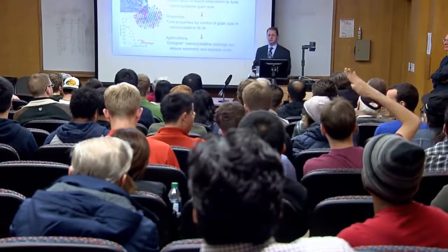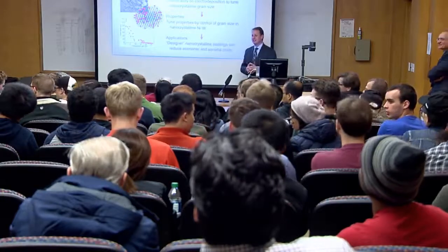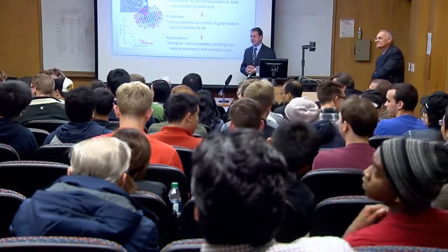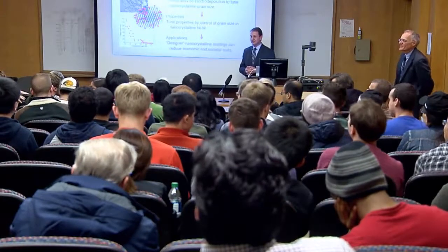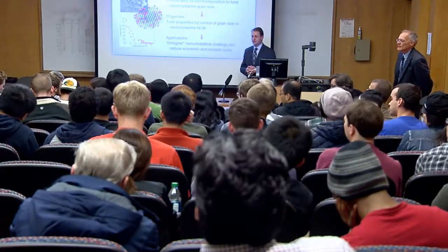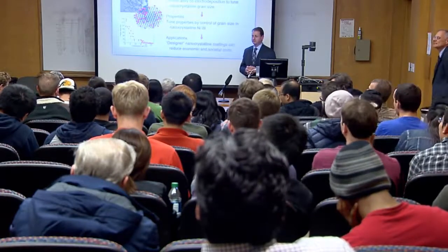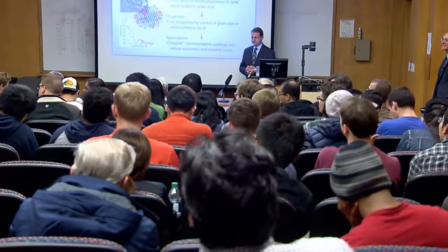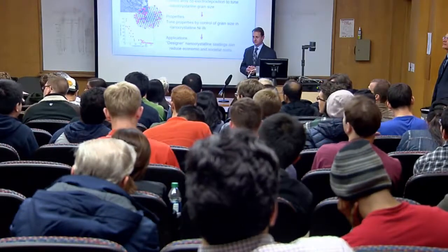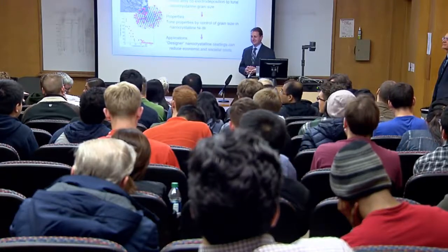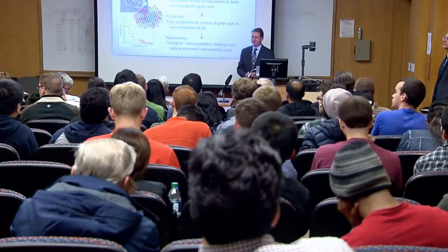Yes, the tungsten-nickel system is known in the tungsten metallurgy field as one where nickel segregates heavily in tungsten, because tungsten has very low solubility. And when it segregates to the grain boundaries, it does the opposite: it causes exaggerated grain growth. And rapid sintering too, right? Yeah, activated sintering, right? Yes, that's exactly it.